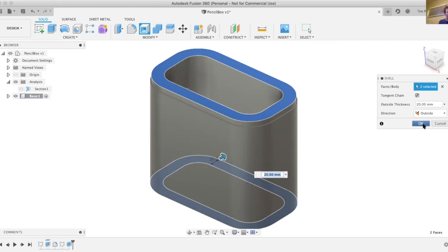They're infinitesimally thin, but you can do a lot of things with surfaces. Once you have a complex surface, if you want to, you can add a thickness to that surface, and as long as it's mathematically sound, it'll give you a thickness, and now you have something you can work with. Another approach is to take the solids modeling approach, develop a solid, and in this case, do a shell.